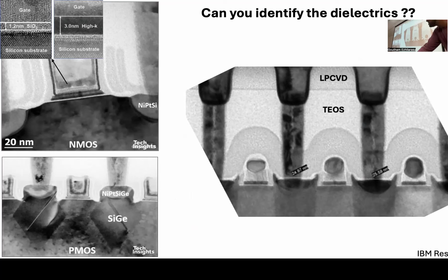No. The low K dielectric is not electrically conductive, right? So the pores are not defects. They just make the effective dielectric constant lower. But they are defects in the sense that they lower the mechanical strength of the material, and they cause it to break down much faster.